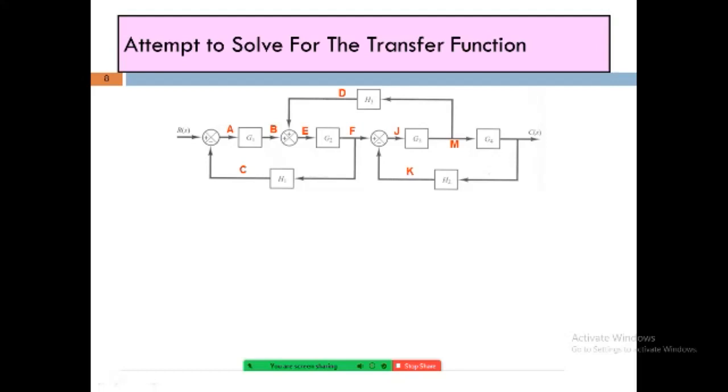Okay, now there are some properties of this transfer function. As it is the Laplace transform of the impulse response for zero initial conditions. Secondly, this transfer function can be determined from the system input and output, by taking the ratio of the Laplace transform of which two quantities? Definitely the Laplace of the output to the Laplace of the input. What is the next property of this transfer function? As per the solution of the equation, the transfer function is always independent of the input to the system.